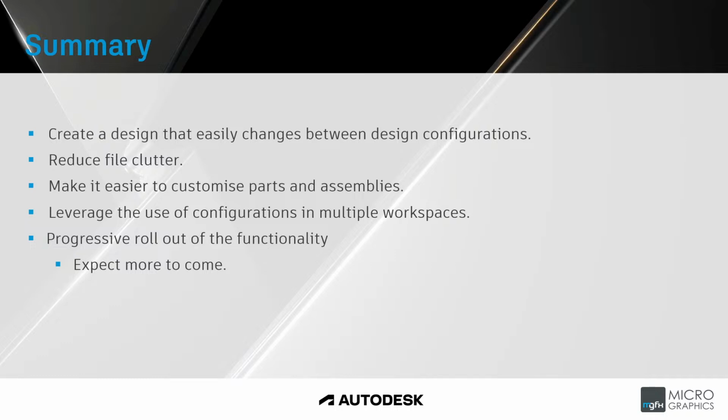Once again, you can also make a change on the design, like add a fillet or a chamfer or a hole that carries across through all 3 configurations, so that when you design, you can have all 3 configurations update as you make the design. Whereas if you had 3 models for the headphone and you needed to add a hole somewhere for a microphone, you'd have to go to each individual file and make that change on each one.